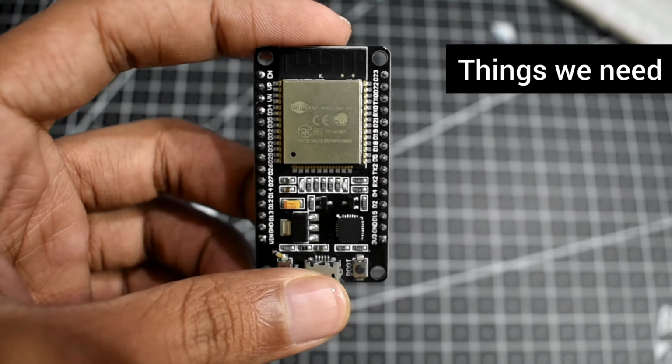Alright. Now it's time to create the instance. So DHT sensor, and here in this I need to specify the sensor. It's better if I copy the definition that I've made on top and paste it here, comma, the sensor type, and don't forget to put the semicolon. So I followed this step from the Adafruit library itself and make the other changes.